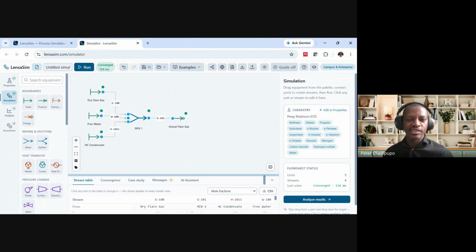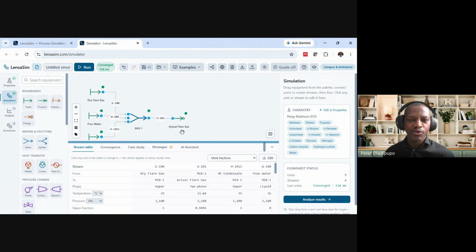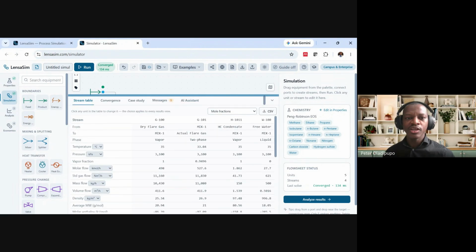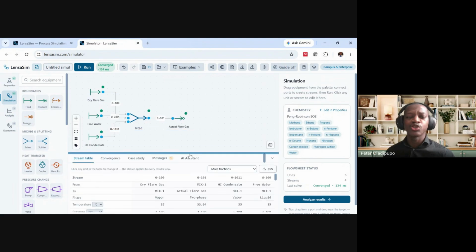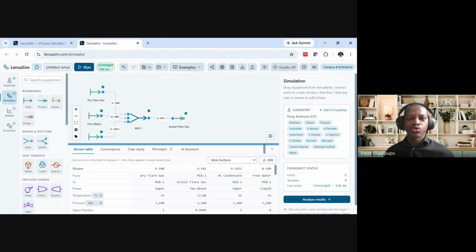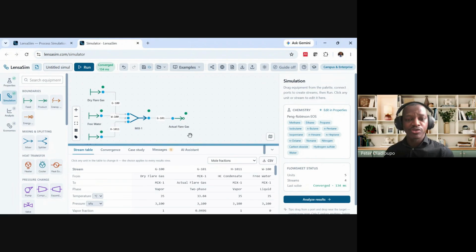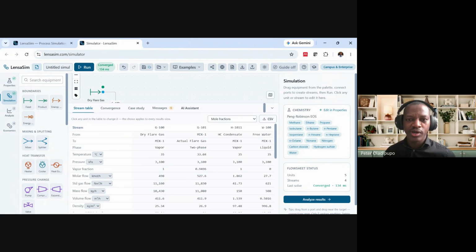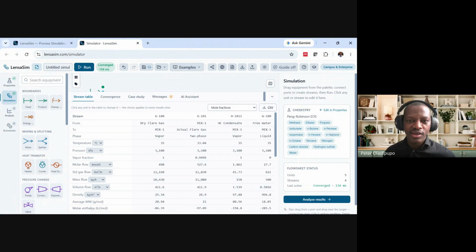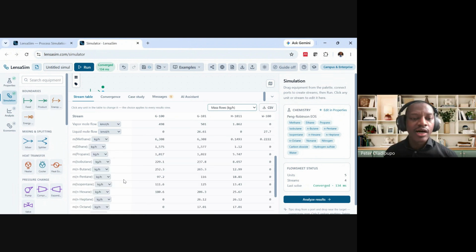All right, so we've run it and the solver has solved the flow sheet, right? So you can see what has been done here, just a simple mix. Nothing is happening, right? Just mix, to have the way the flare gas should actually be before entering the process. So if you look at that, that is G101, right? Stream G101. See what we have here. It's what is being mixed. Look at the composition. Let's choose mass flow rate as the basis, so we see what we have.